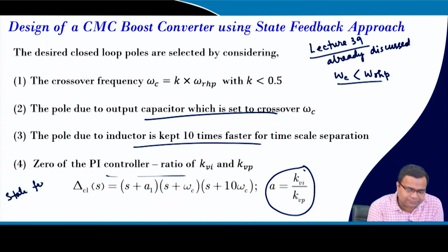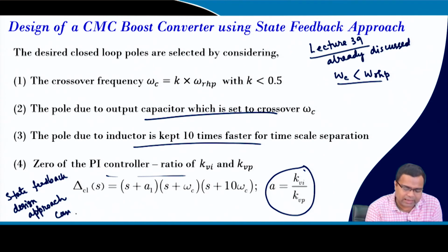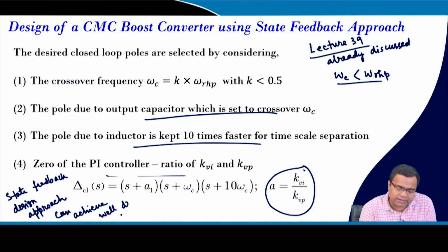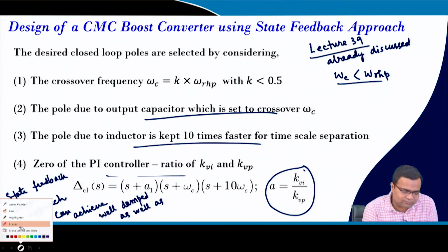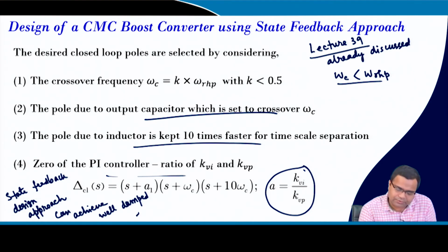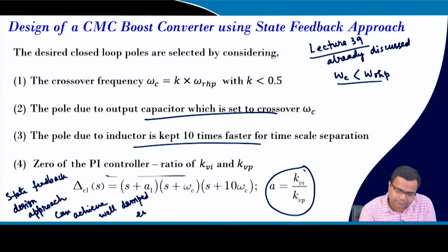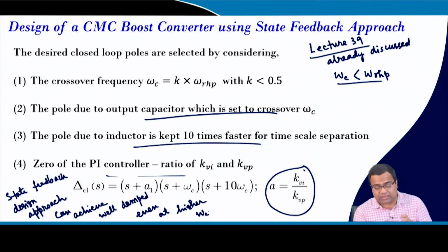The state feedback design approach can achieve well damped as well as faster well damped response, even at higher crossover frequency, because that is the problem in output feedback design.